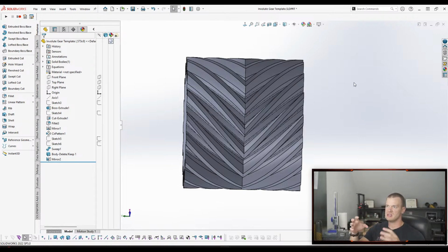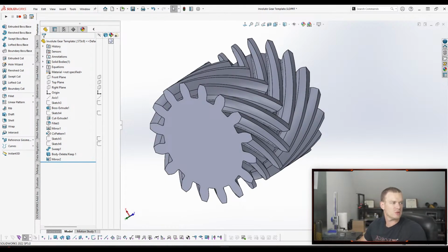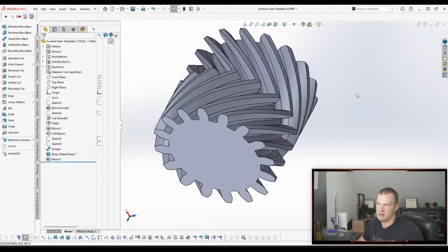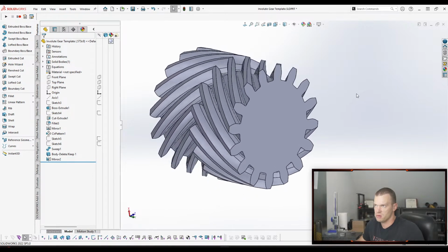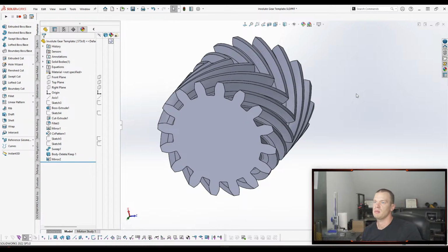axially. So with this type of gear, you have counteracting axial forces, so you have all the benefits of a helical gear, but without the axial force that you have to take into account. So this, I think Coral said that this was going to be 3D printed. So this would be ideal because it'd be relatively inexpensive to make this type of gear using additive. So that makes a lot of sense.